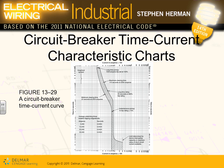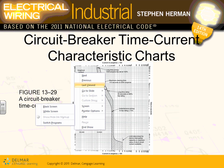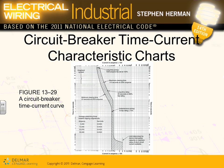Ground fault? Okay, now Matt, if you remember, in the commercial project we had a time current characteristic curve. Every circuit breaker has a time current characteristic curve. This curve will decide how fast my circuit breaker will trip, and I'll show you in a second. The higher the current, the faster the circuit breaker will trip, and that's called the time.